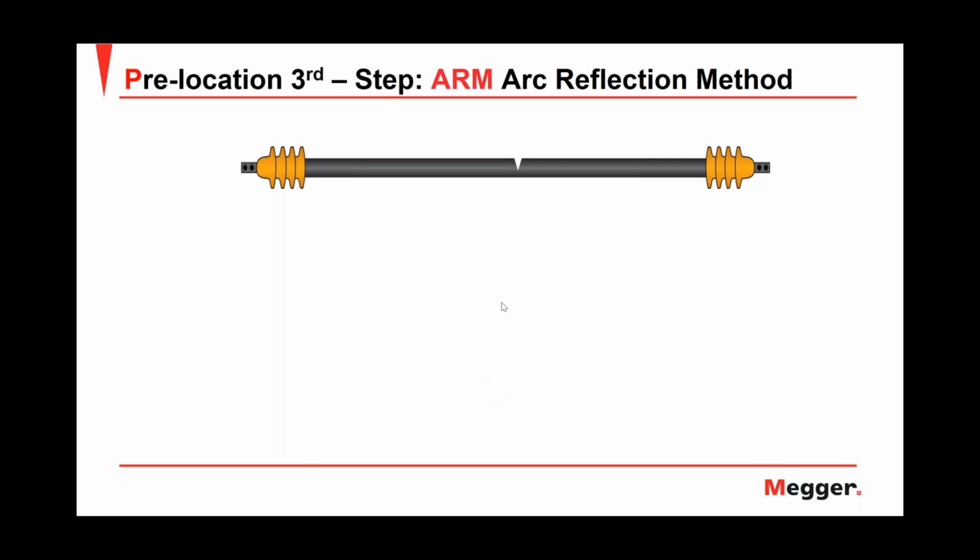Let's consider that we have a medium voltage cable. Let's say that it's a cable of 15 kV, and we have a pinhole fault over here. And this pinhole fault needs at least 4 kV to flash over. That means that the breakdown voltage of my pinhole fault in this cable, the flashover, is at 4 kV. That is the breakdown voltage, 4 kV. Well, the first thing I will need is to use my TDR and my thumper to get the reference trace.